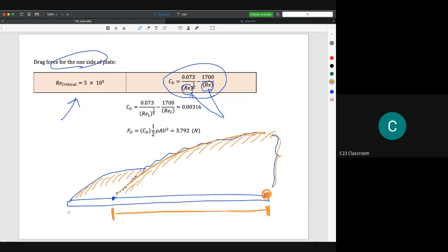It does not take care of this distance. Also, if we change the distance here with the total distance of the plate, it means our boundary layer starts from here now, so we create a bigger range of boundary layer, and the delta here does not reflect the real situation.